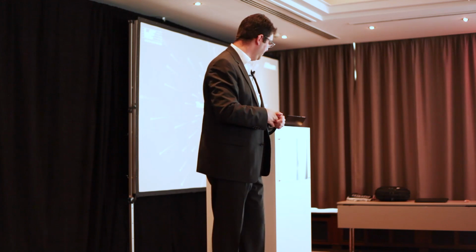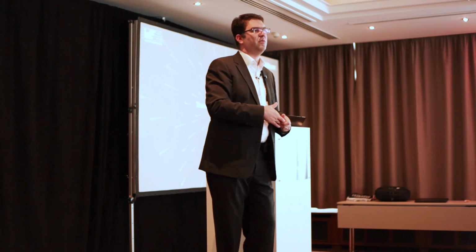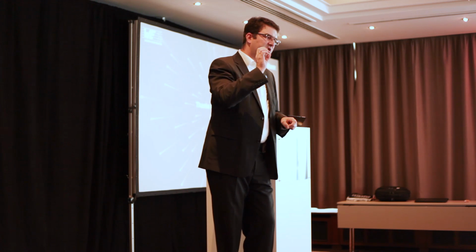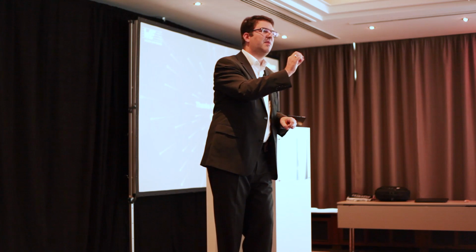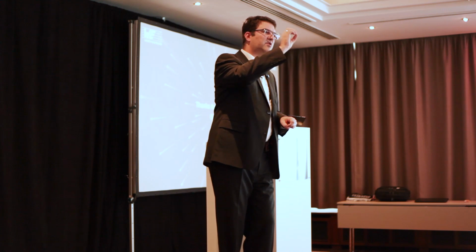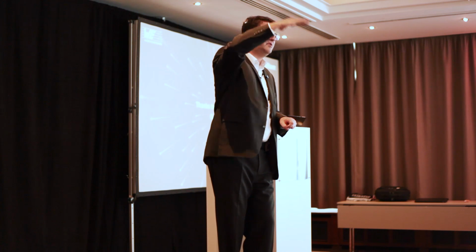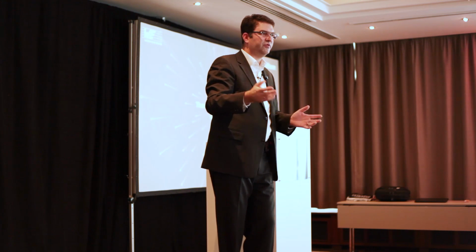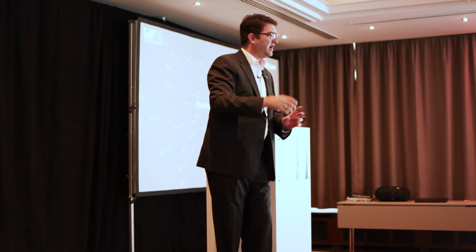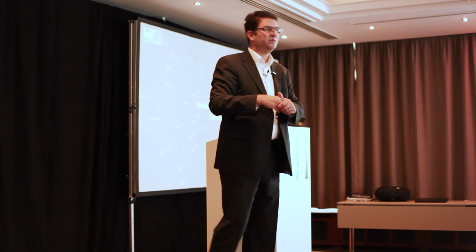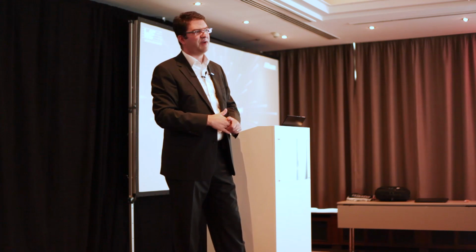Let's take the example of MOSFETs. You can sinter them onto this core. And when you use a 100 micron core, you can already make a microwire in that 100 micron core. So connecting the sinter part, and from the other side, make the microwire on the top for a source and for the gate, for example, connect it there. And you still have the double-sided connection. So it may be possible, yes. It depends on the component, depends on the setup and so on, but there are ways to do this.